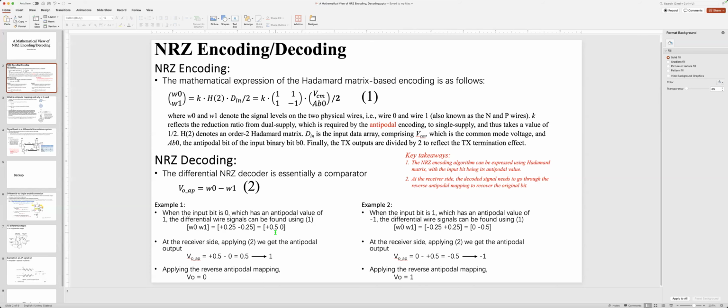However, if you feed the signal through a capacitor, at the capacitor side it's plus or minus a quarter volt around the common mode voltage. So that's why we see a quarter volt here. And at the receiver side, if we use this voltage swing, we will get the same thing. Use either one, we get the same half volt, and half volt is scaled to 1 volt.